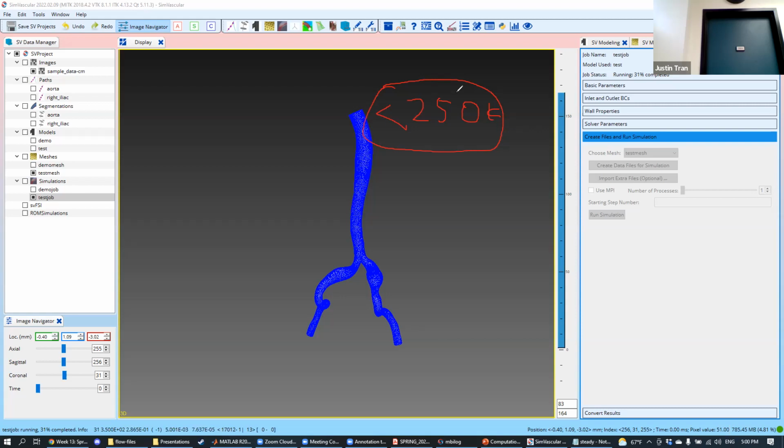Okay, and so what you can do here is that you see this button for mesh, and so you can try to remesh each individual face. So you click on this, click on estimate, click on remesh. This is one way to kind of narrow it down. If you try to mesh each individual one, there might be one that gives you that error, and that tells you what's wrong. Once you go through and work with that.